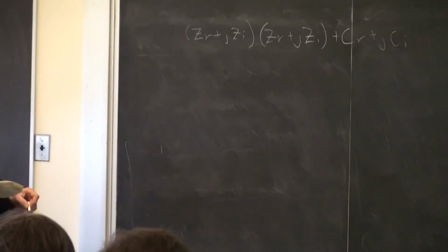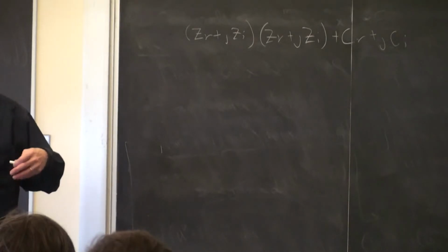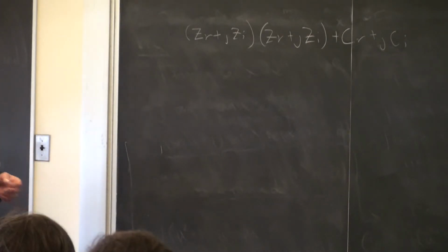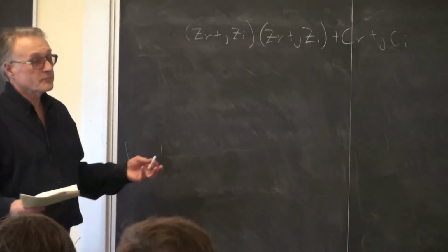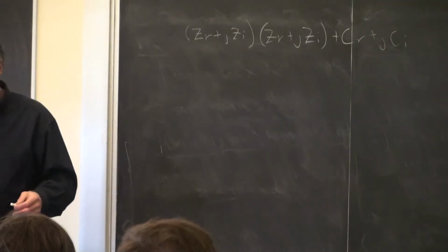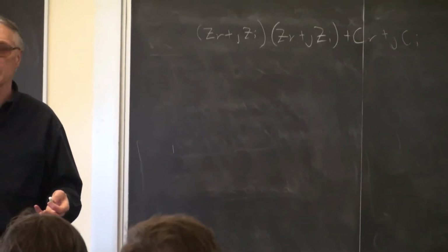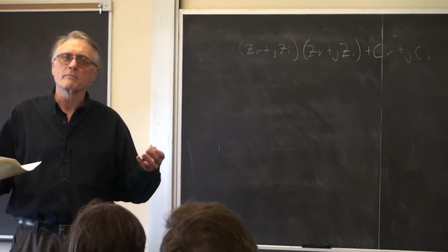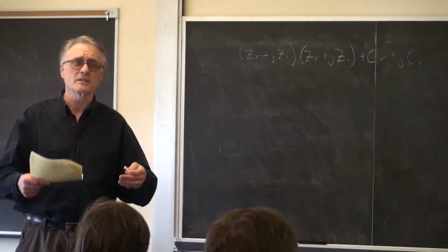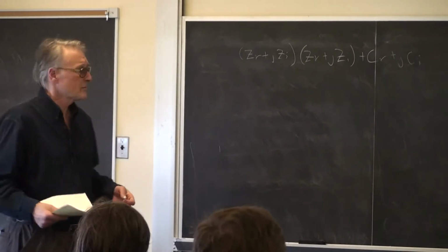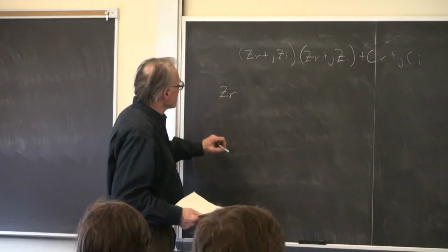We're going to want to convert this to a hardware description. So what I did was first write out a kind of block diagram of what operations had to occur, and then I tried to merge them, and then tried to minimize the number of cycles necessary to make that go. So if we go through that process, we have some z real as input,